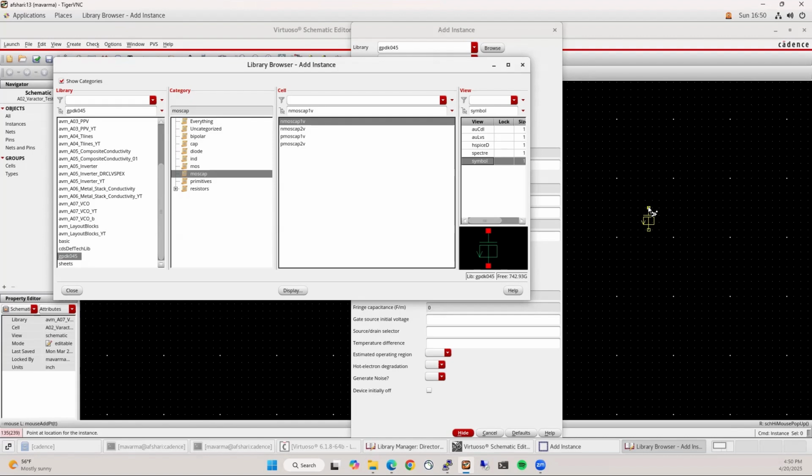So if each transistor has its own body, for example, if it has a P well and a deep N well, where you can separately bias the P well and deep N well so that the bodies are separate, then you can have a negative voltage for your MOS varactors. If not, just connect the drain, source, and bulk together, and then just use the strong inversion region or the accumulation region, depending on what kind of model you have. Okay, so in this case, we will go ahead and use the NMOS cap.